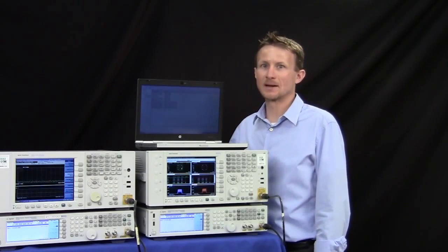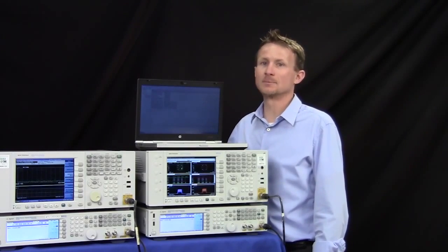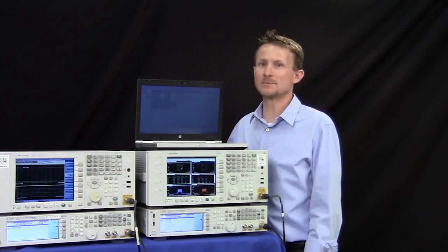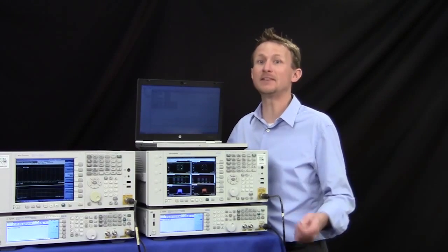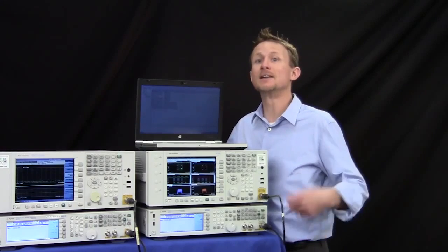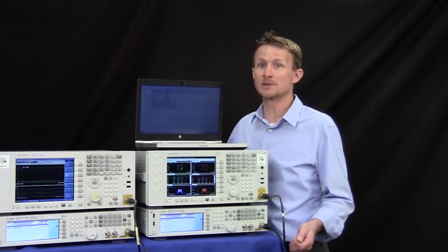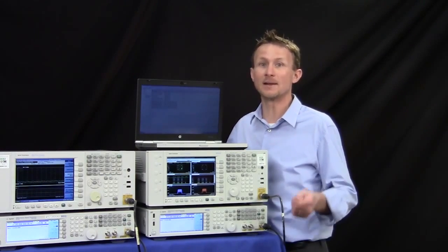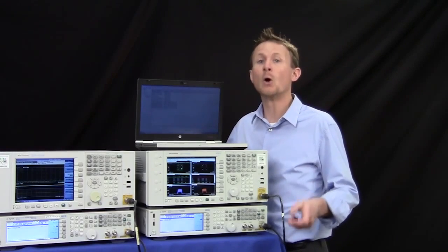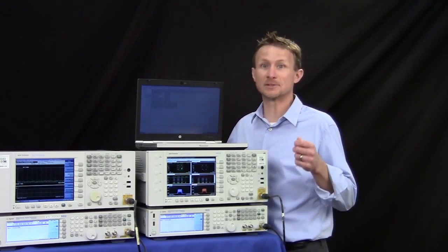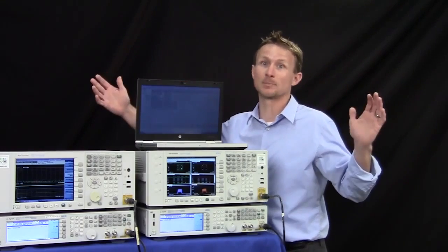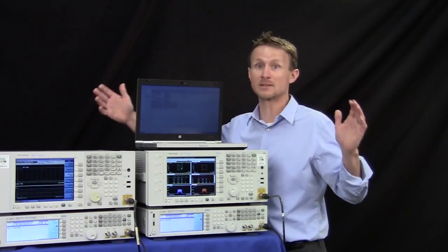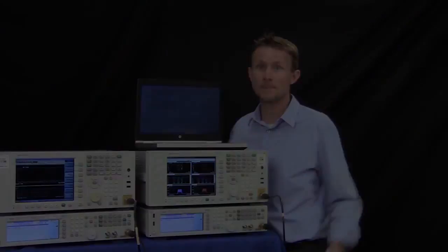From the base station perspective, we have multiple component carriers that are being transmitted, and each one of these must maintain strict RF requirements in terms of ACLR, EVM, and spectral emissions. Additionally, each of these component carriers must maintain strict RF timing alignment with respect to each other. One of the test challenges is being able to simultaneously measure these component carriers, which can have frequency separations wider than the bandwidth of a single analysis instrument.